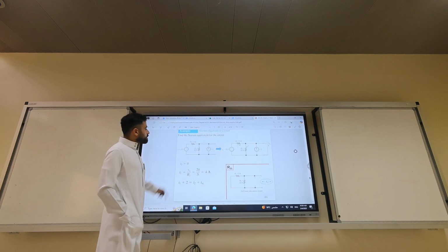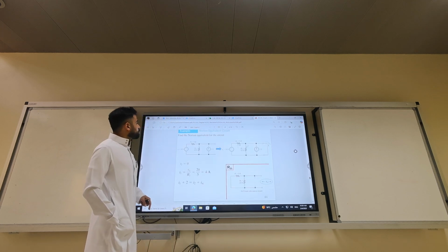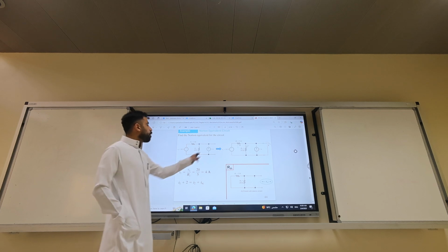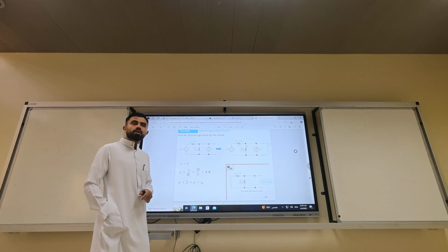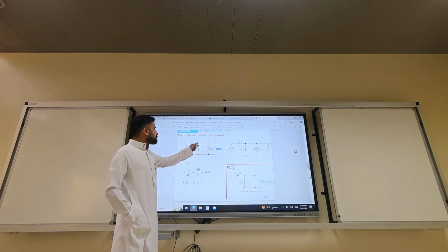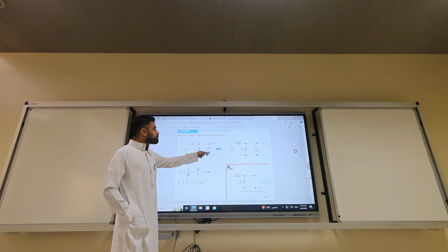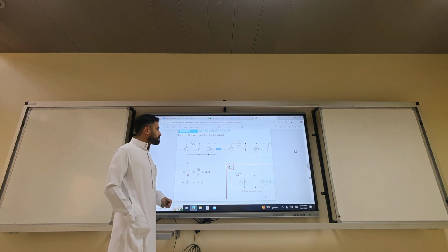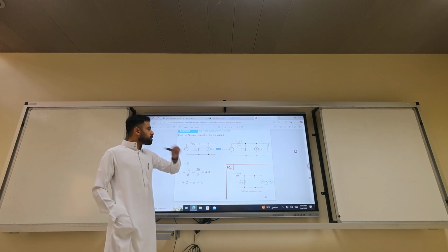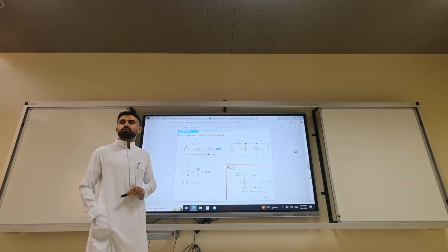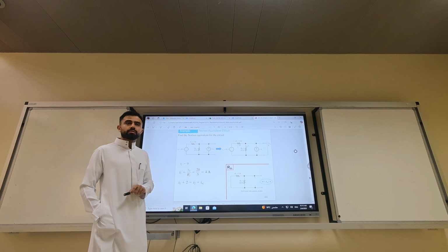We did another bigger example where we find the Norton equivalent. In this example I solved last time, to find V open circuit, I did a node voltage. So it's V open circuit minus 20, V minus 0 over 20, minus 2 amp equals 0. One variable, one unknown. We find V open circuit. R Thevenin is you remove the current source, you short circuit the voltage source, which is 20 parallel with 5, which is 4. Okay?